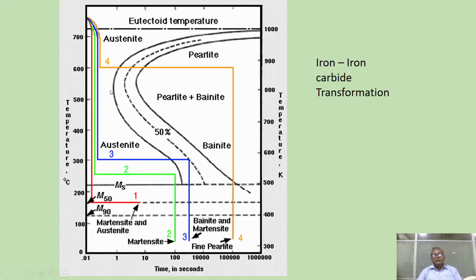So that is very important. This is for that purpose. TTT diagram will tell you how to get a different microstructure by cooling. Okay, so that is the main purpose of this TTT diagram.